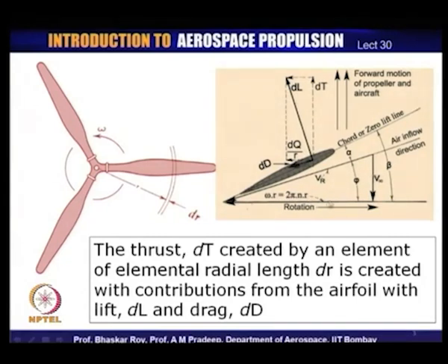So, the two of them together make up this resultant velocity V_r, which is now said to be actually incident on the propeller at this particular section. So, this particular section now has to be aligned as close to this direction of the resultant velocity. Now, this resultant flow is at an angle phi with respect to the peripheral direction or tangential direction of the